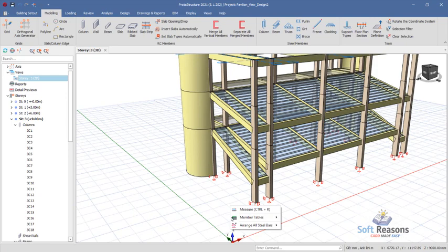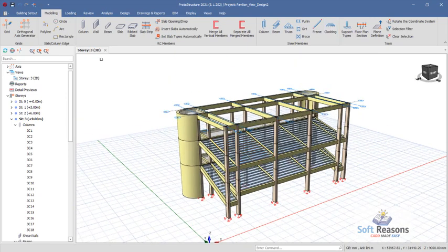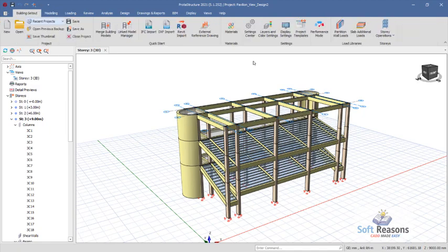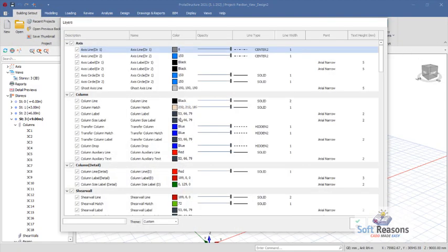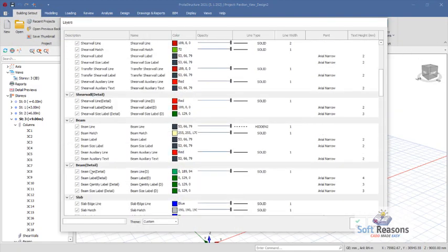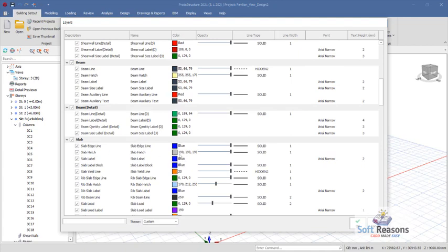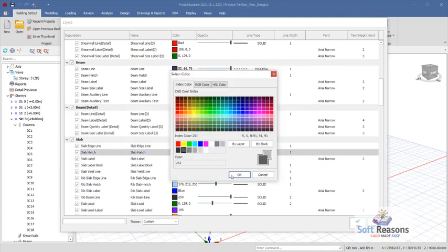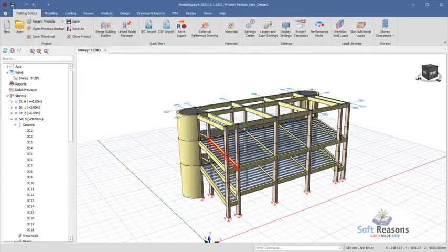You can as well make the slab solid so you can see it very well by navigating to the building setout, come to layers, properties, settings, and then come over to where you have slab ash right there. Change this to this one, make it a little bit darker. Okay, options, so you have this.